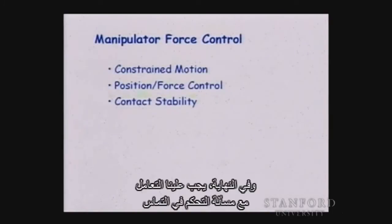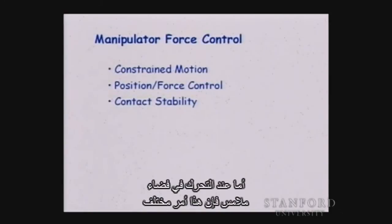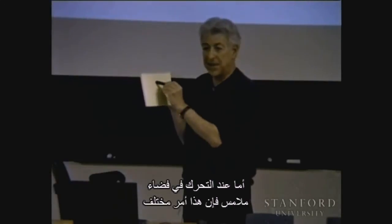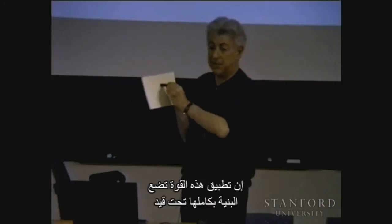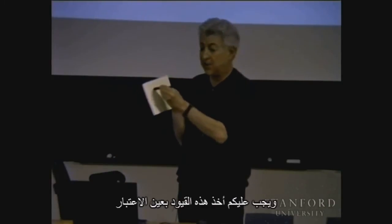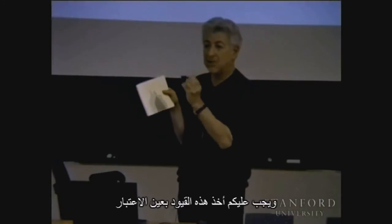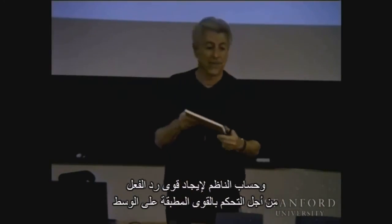Finally, we need to deal with the problem of controlling contact. Moving in free space is one thing, but moving in contact space is a different thing. Applying this force puts the whole structure under a constraint, and you have to account for these constraints and compute the normals, to find the reaction forces in order to control the forces being applied to the environment.